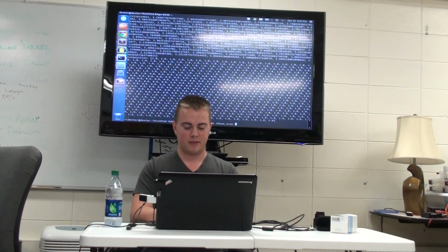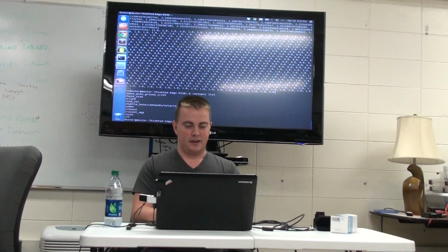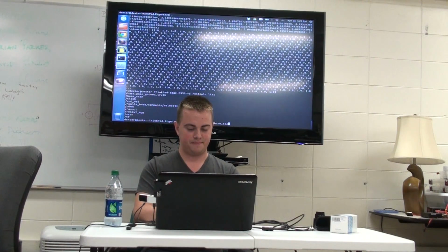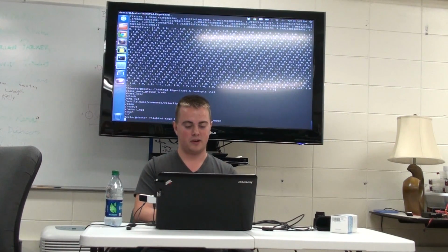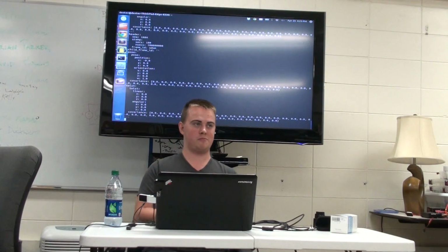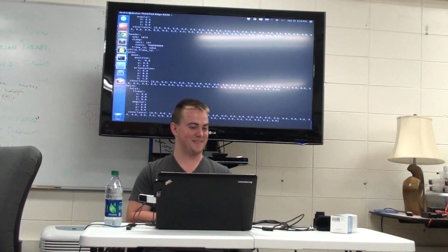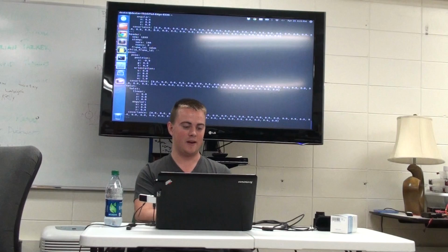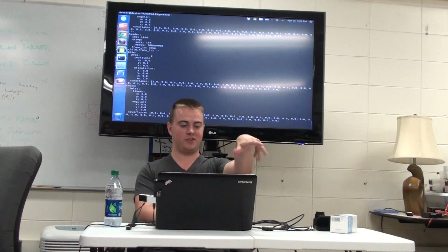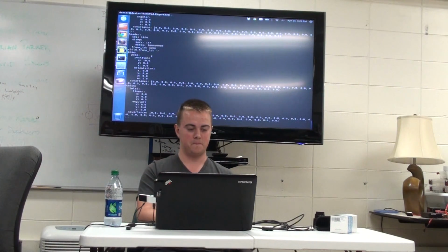And then let's say we want to see odometry. We can do a similar thing. Also echo odom, and again we're getting odometry messages. The robot hasn't moved, so it's just sitting in place. So this is an odometry message for reference. It has position and orientation, essentially your XYZ coordinate in space as well as your angle. Yep, that's odometry. It's 0 because there's nothing happening.